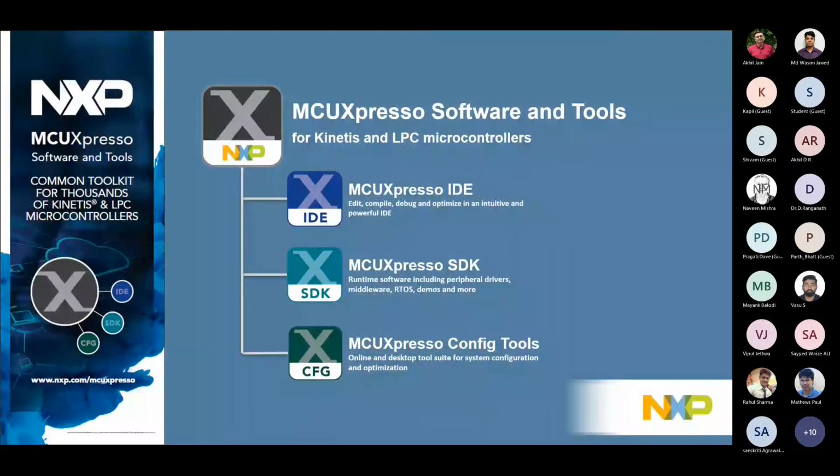Okay, so let's start with MCUXpresso. MCUXpresso tools is itself a complete tool. It provides you the integrated development environment, the IDE, where you can write your own embedded code to burn to the chip for the final applications. And to develop the code, you need to understand the MCU, its peripherals, the clocks and everything. So either you go through all the 1,000 pages of the MCU reference manual and then start writing your own code for the peripheral initializations and everything.